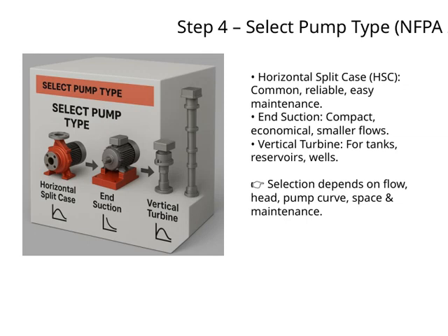All right, now we're at step 4, which is selecting the pump type according to NFPA 20 standards. When choosing a pump, the most common type you'll encounter is the horizontal split case, or HSC. These pumps are popular because they are reliable, easy to maintain, and generally have a long service life. They're a solid choice for many fire protection systems.